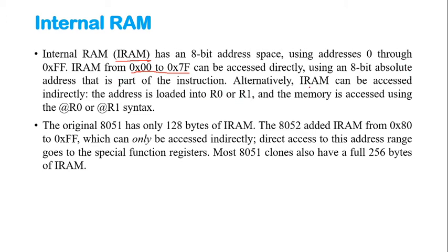Alternatively, IRAM can be accessed indirectly. The address is loaded into R0 or R1 and the memory is accessed using @R0 and @R1 syntax.